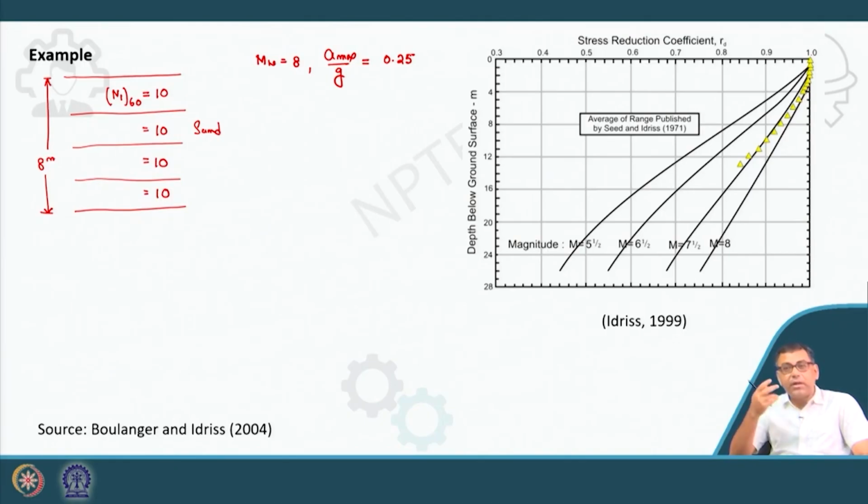So suppose you have another magnitude with you, that is surface wave magnitude or body wave magnitude or local Richter magnitude, then the chart is given. So you can use this chart and convert those magnitudes to moment magnitude. The use of those magnitudes has some limitations. Follow those limitations also, then convert it to moment magnitude, and then you can use the moment magnitude, or directly you can measure the moment magnitude itself.